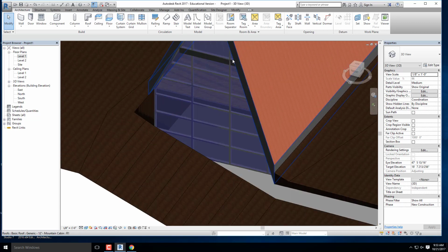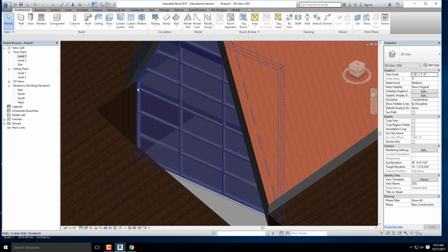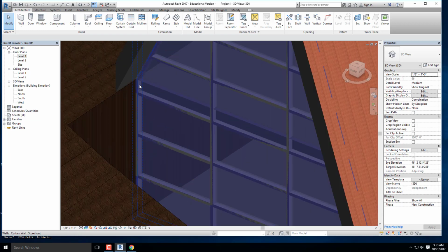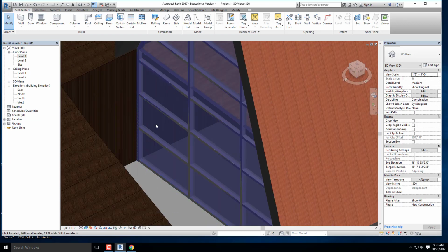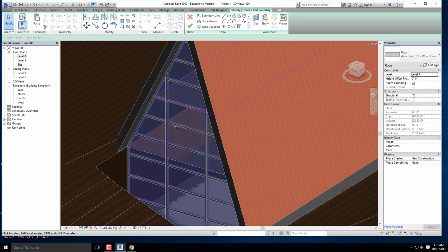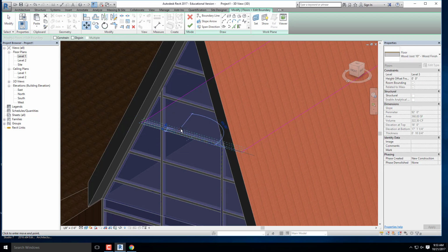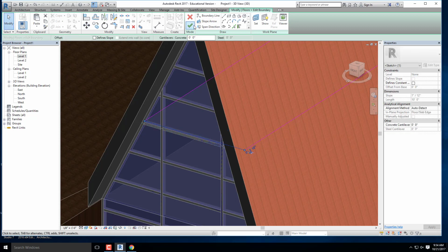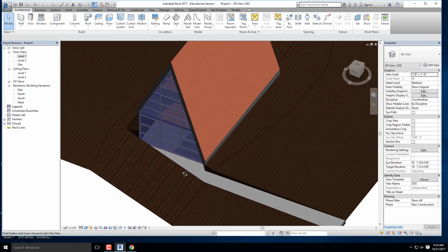You can see here that we actually still have an overlapping floor. That's why I indented that wall assembly just a little bit. You can see there that it might still be overlapping just a bit, but again, I can click on that floor assembly, go to edit boundary, and I think this curtain wall is actually 5 inches thick, so I'm going to move it inside 5 inches, and hit the check mark. We all see that? All right, so we're getting a little bit closer.